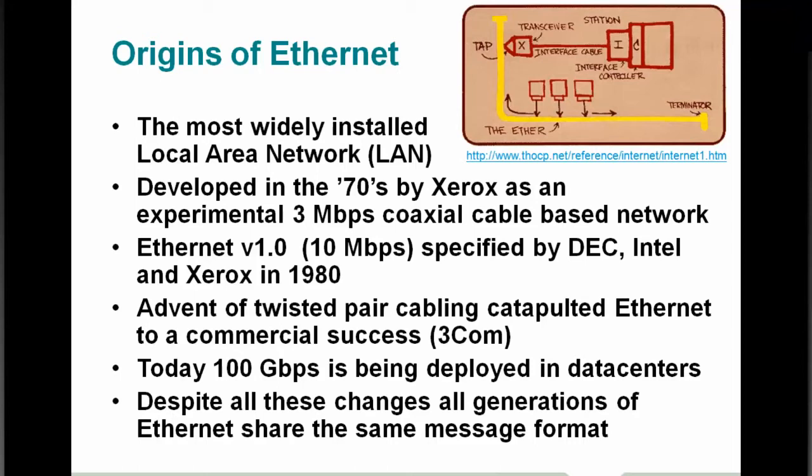Fundamentally, it's gone from coax cable to twisted pair over Cat5 cable that a lot of you are familiar with. We started with 10 megabits per second, and it's gone to 100 as commonplace. Perhaps a lot of you are looking at gigabit as standard for industrial applications. In the data center or more in enterprise IT applications, they're doing 10 gigabit and even 100 gigabit in some of the leading institutions.